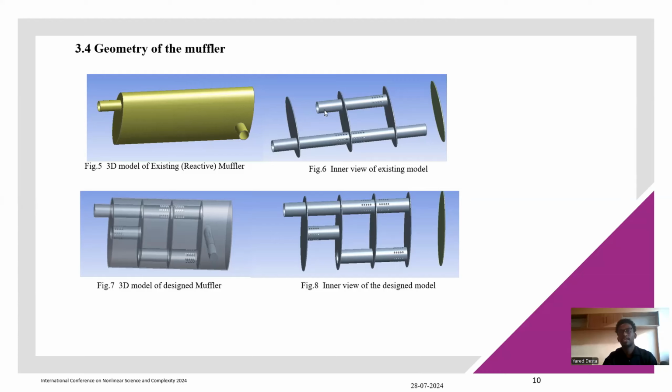So there is a noise cancellation that occurs in between these baffles, and finally, due to the pressure difference, the gas gets out from the first chamber, moves back to the second chamber, circulates here, gets into this perforated area, and goes out through this pipe.